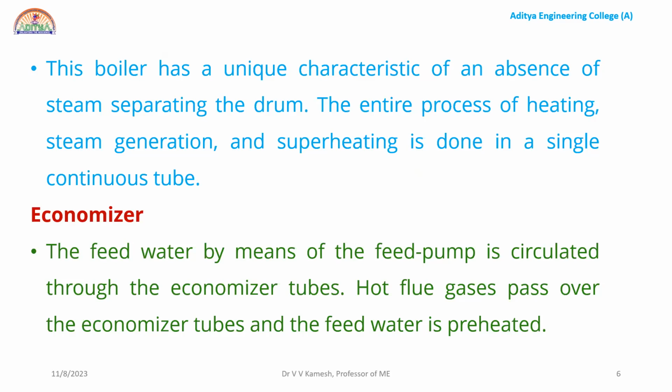So this boiler has the unique characteristic of an absence of the steam separating drum. Without the drum, we are very happy because we need not worry about the scaling and other factors. Directly the water enters one area and steam goes out the other end. The entire process of heating, steam generation, and superheating is done in a single continuous tube.